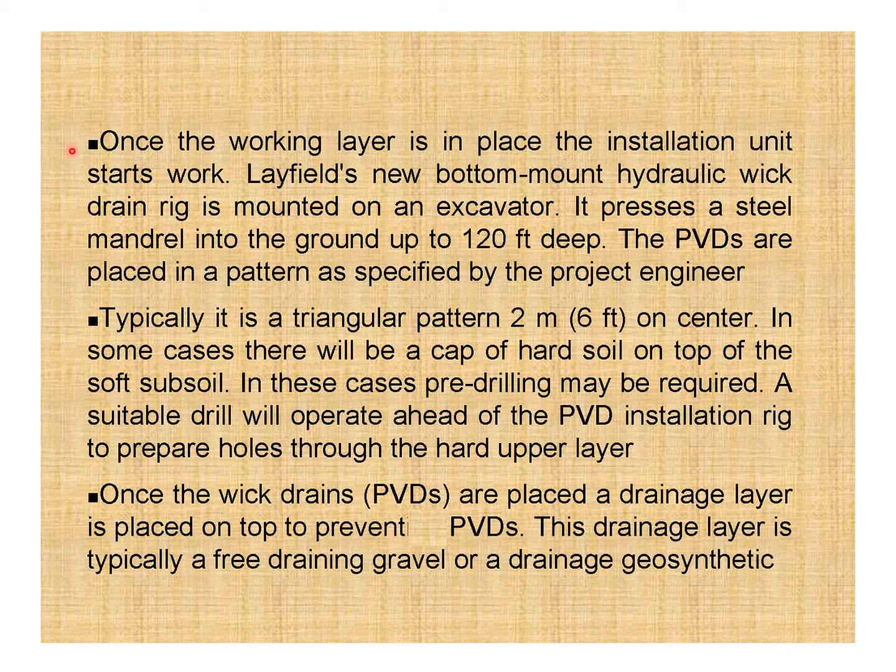Once the working layer is in place, the installation unit starts work. Layfield's new bottom-mount hydraulic wick drain rig is mounted on an excavator. It presses a steel mandrel into the ground up to 120 feet deep. The PVDs are placed in a pattern as specified by the project engineer. Typically, it is a triangular pattern, 2 meters on center.